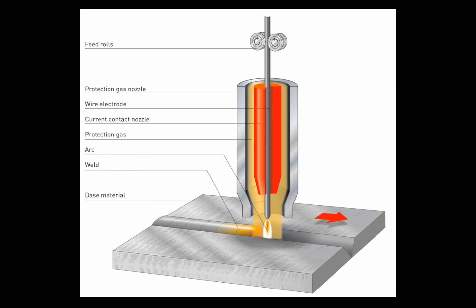What is the purpose of using flux when welding aluminum? Flux removes oxides. By combining with them, flux dissolves below the surface of the puddle and floats the oxides to the surface where they can be removed.